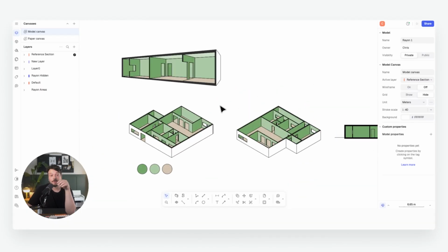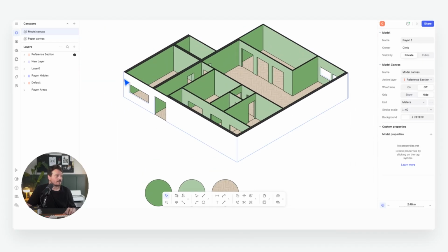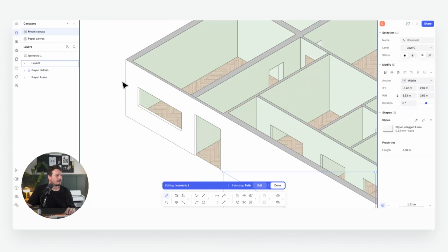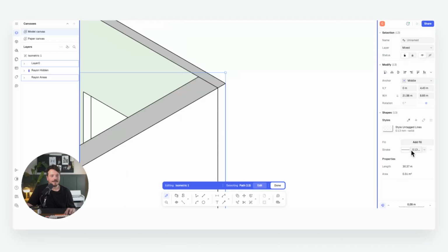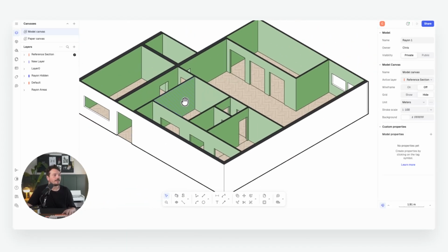Another couple of things which may help your illustration style would be to look at the line weights and some shadows, for example. So one thing I tend to do is to make this outer line slightly thicker. It helps read on the page. So I can go into here, select the lines that I want, and then give them more of a thickness. So let's say 0.5, for example. And you'll see there, it's got more of a defined edge.